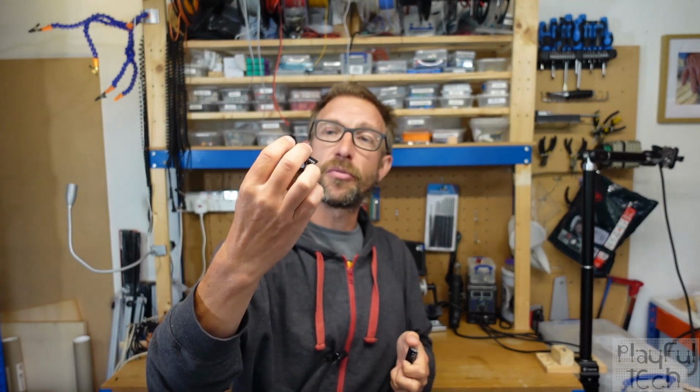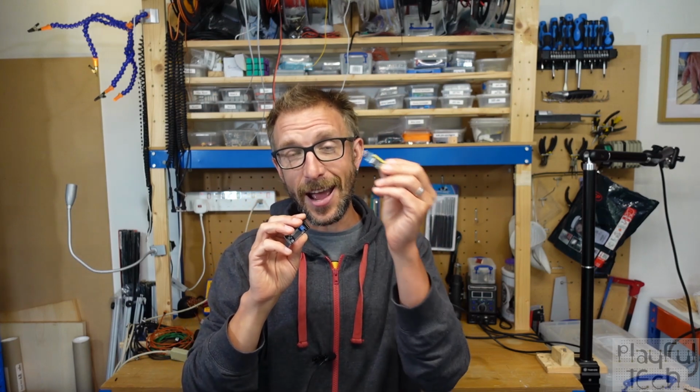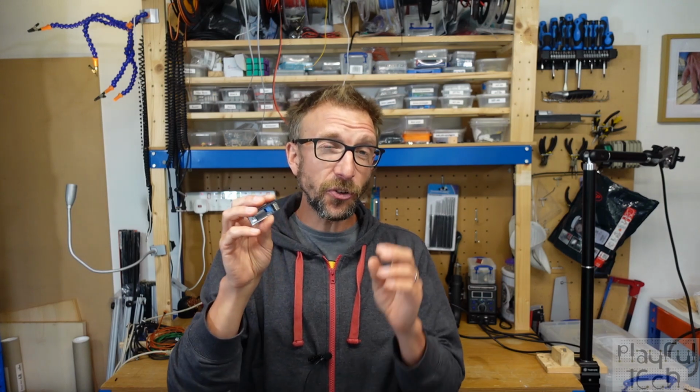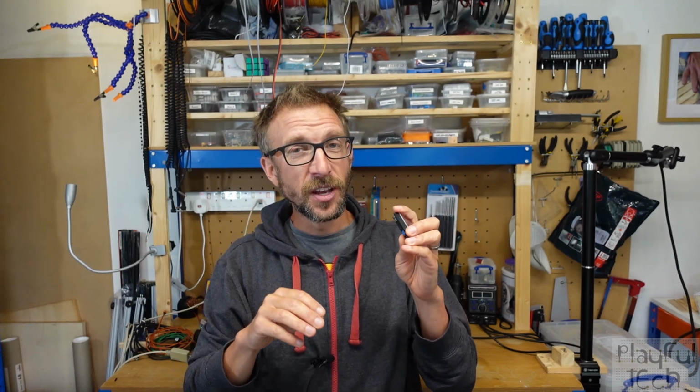Now, there are some alternative port expanders I should mention as well, and the most useful one of those is one of these. This is an MCP23017. Now, this chip does have built-in pull-up resistors on each of its channels, and it's also got 16 channels rather than the 8 of the PCF8574. And each of those channels also has individual interrupts. So it's much closer to having feature parity with the inbuilt GPIO pins than the PCF chip does.